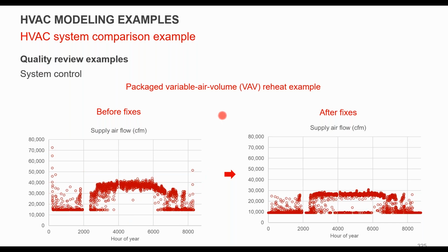These are not generated automatically, but it is fairly simple to export that 8760 data set out of the model, and a lot of tools will export it for you. Then you just dump it into Excel or another spreadsheet tool to generate these kinds of plots. More and more you're seeing graphical interface support, so some tools do have ways to look at the output directly, and some you might have to export and visualize yourself.